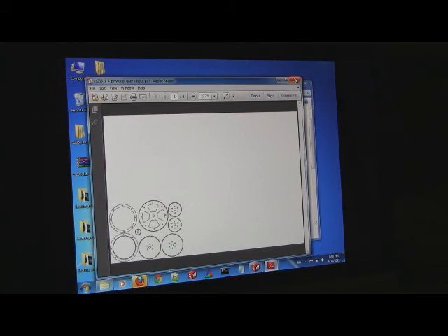a couple things from laser cutter files. I need the size to be 1219 by 1219. I need everything to be in the lower left-hand corner. I need it to be set up in terms of where the parts are, exactly as mine is. And I need all the crosshairs and all the text and all the dimensions to be gone. As long as you got that, we're good to go.